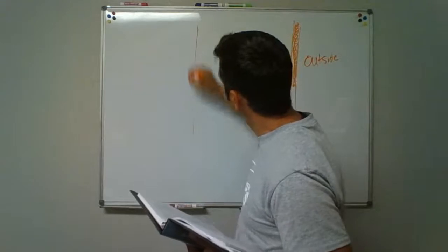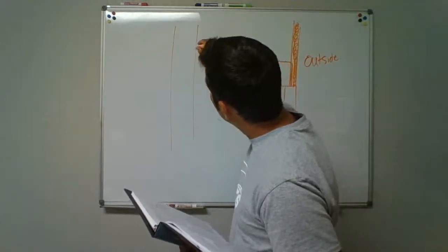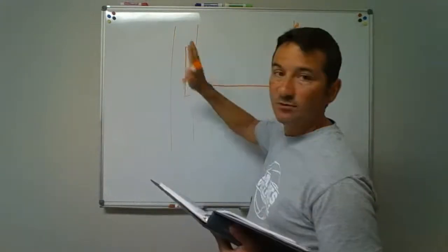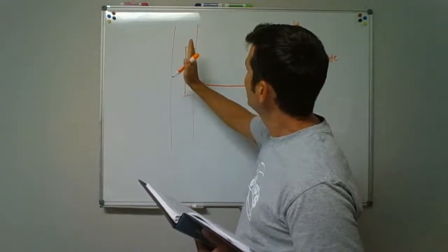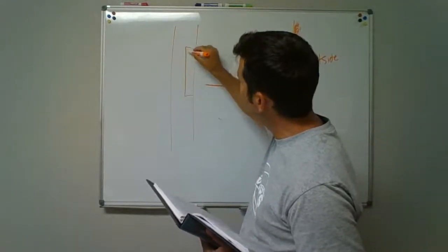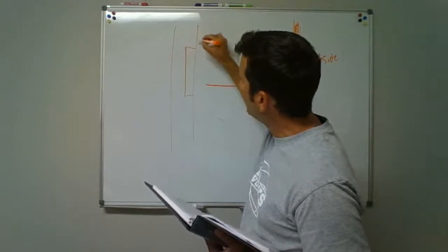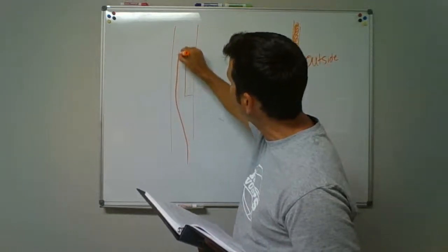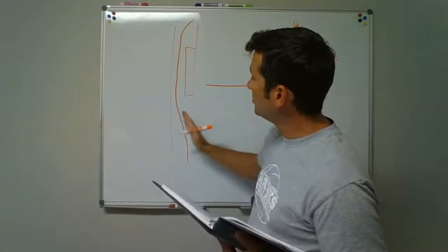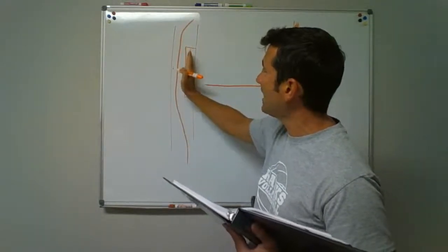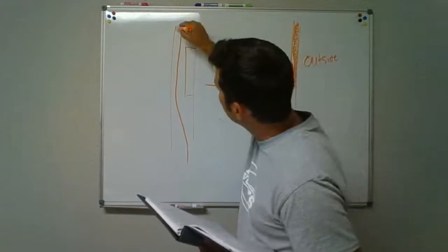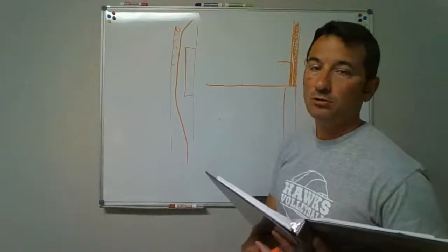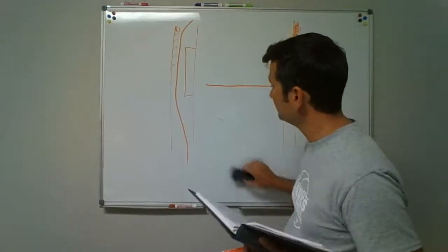So let me blow up the wall here. There's the thickness of the wall. Some of this space is taken up because they've got a 2x4 block between, you're looking at it from the side end. So this block is going between a stud and a stud. That's taken up 1.5 inches of the 3.5-inch stud. So our water line is going to have to actually flex and go behind that. Once we flex the water line and have it running behind the block, there's not enough area to get insulation in behind here. So what we'll do is we'll pipe wrap that water line to keep that thing from freezing.